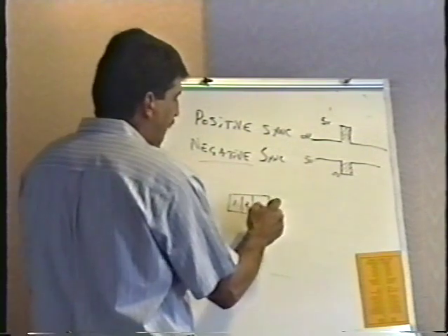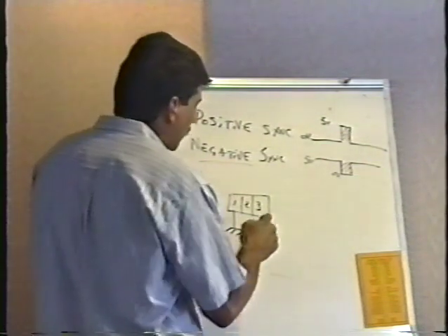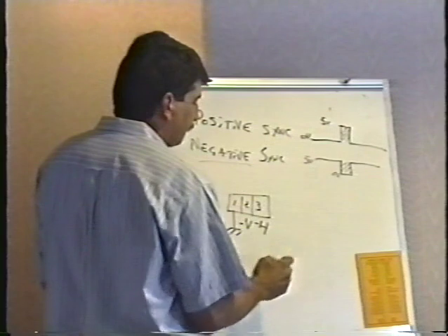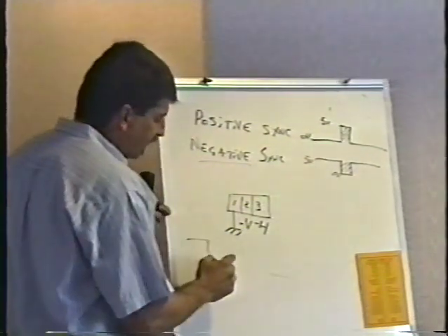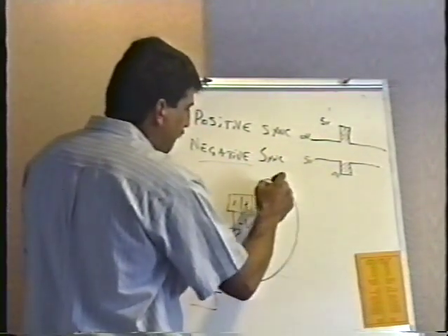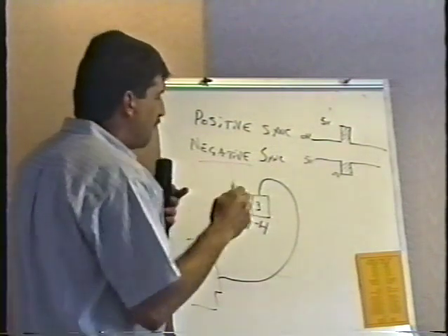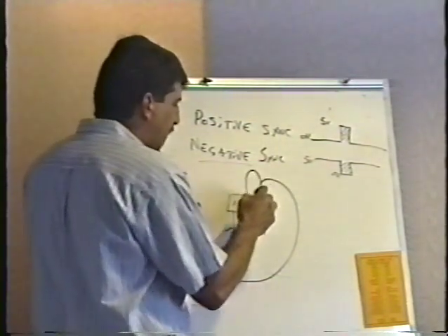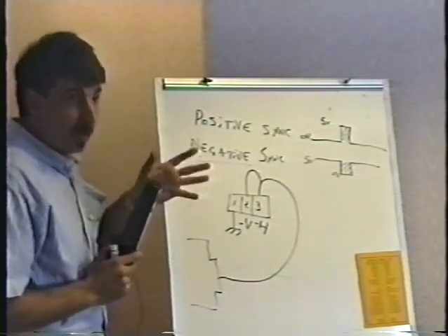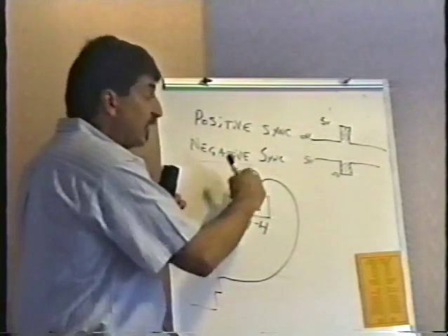Pin 1, 2, 3. Pin 1 is the video ground. You may choose to put that on pin 4. Pin 2 is for the negative vertical, and pin 3 is for the negative horizontal. You should take the composite sync that comes out of your logic board, out of pin P, and run it only into pin 3. What some people do is put a jumper to run the composite sync into both pins 2 and 3. On the Electro-Home monitors, and we'll look at these things in great detail later on, you do have to put that jumper in.